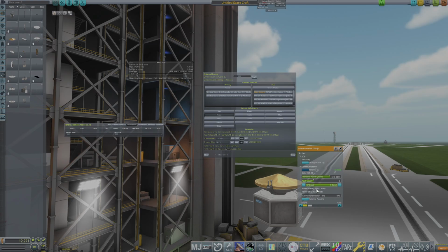But you can also see it's taking a lot of power. It's taking 170 watts if it's transmitting to Earth. And that's the power drain you have transmitting data to Earth from your experiments. And it's quite high, especially for early on. So the question is, is it really worth it? Do your mission planning. If you can say, well, it's not 250 gigameters, it's only like 200 in the mission time frame, and then you plan it properly again, and you can probably get down a bit here, like 41 decibel, and then reduce that from 170 watts to like 116. That's up to you. You can do the mission planning.